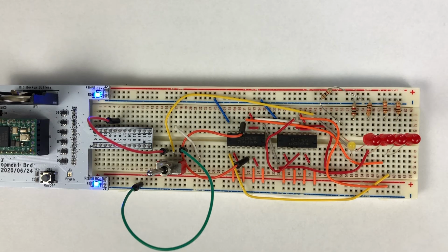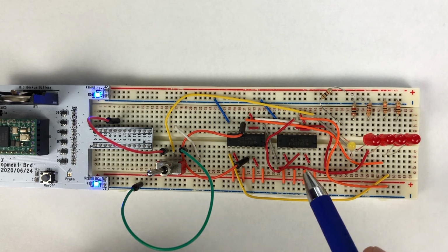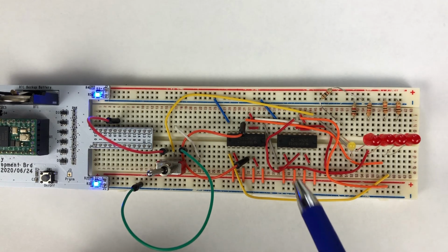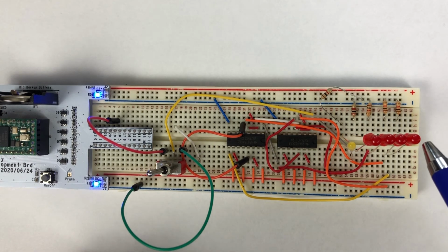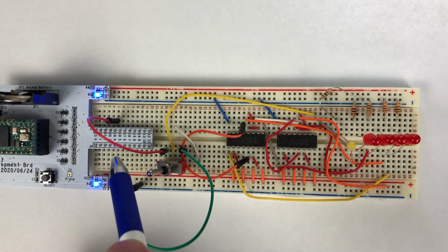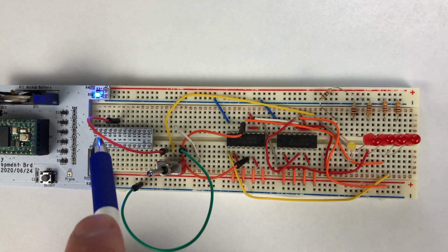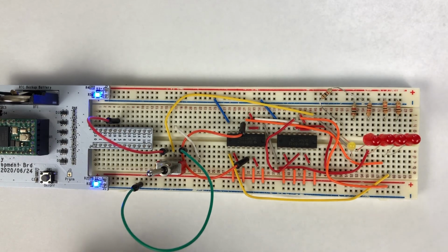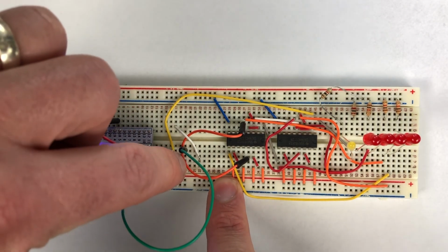Okay, so here is a 4-bit counter fed by 2 JK flip-flops, and they're both in toggle mode. So as discussed, the output Q of each one goes into the clock of the next one, and the readout is given by these LEDs here. The clock itself, instead of manually toggling it, is just fed by this Arduino, or Teensyduino actually, at 4 Hertz from one of these pins, and I can pass it through by flipping the switch. So let's do that. Let's start counting.